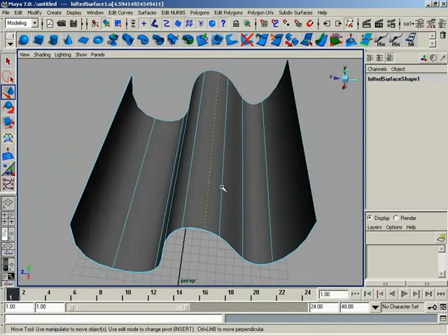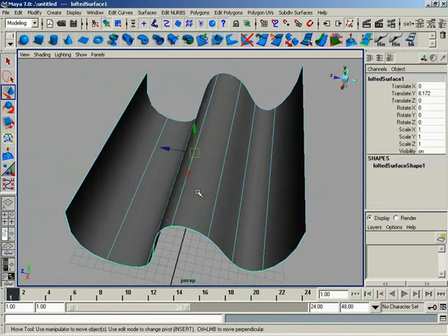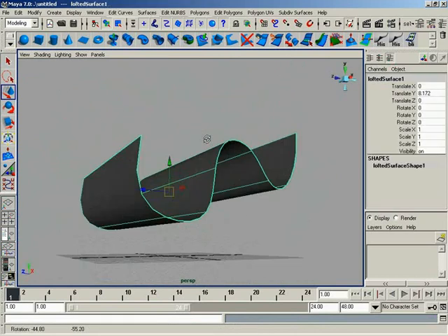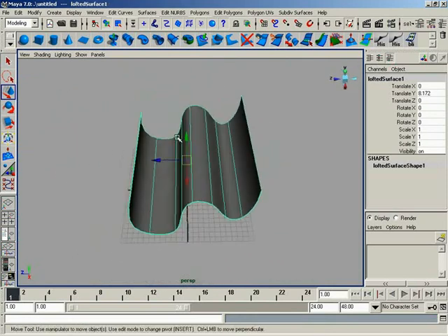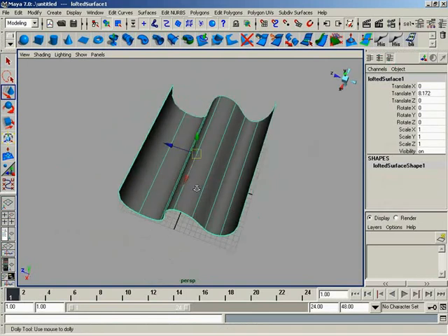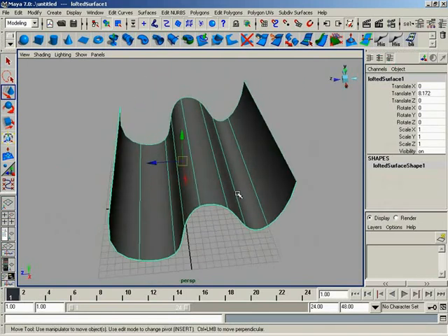And it's because we have this cross-hatched network of curves that we're able to get a surface from a NURBS object. That's really all I wanted to get across to you, that when you're looking at a NURBS surface, you're really looking at curves going off in 2 separate dimensions, which is going to be very important to remember, that bidimensionality of a NURBS surface, as you go to perform a variety of operations.